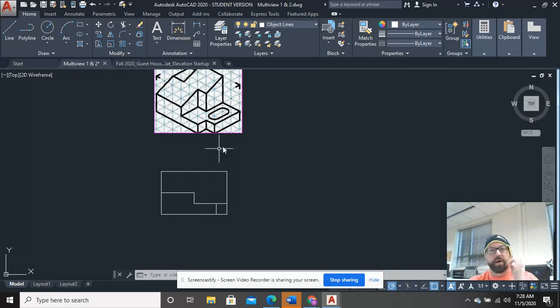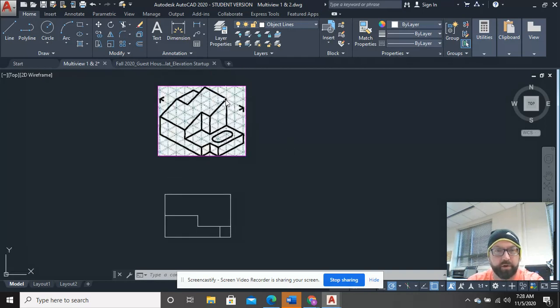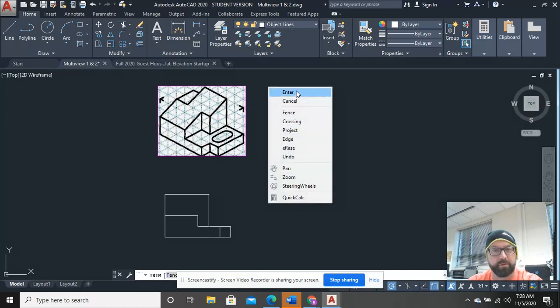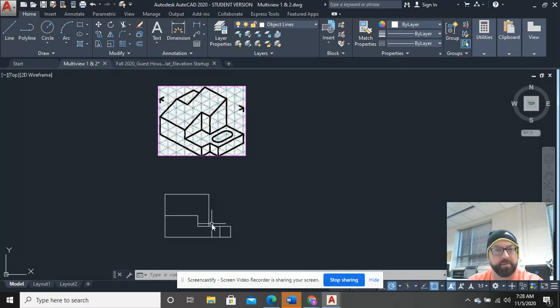Okay, so now let's deal with getting the tallest point up here. All right, so if I work off of this, if I come over 2, I'm going to go up to a height of 3. So in this case, I'm going to offset this right side, the right edge, over 2. And guess what? This completely corresponds because a height of 3 here, right, plus the 1 here is equal to 4. So it's the same. So that's like plugging in your answer in math. So I wouldn't see that going through that face, that front face of the object, nor do I see anything on the right, right? So that's pretty straightforward.